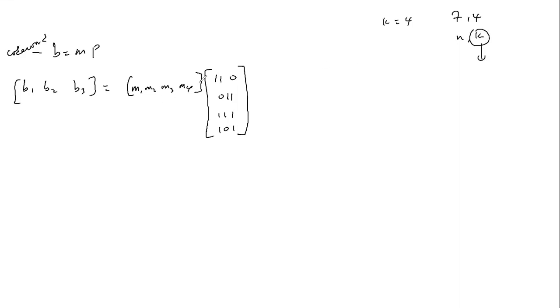So with this, we can develop the system of equations, such that B1 will be the same as M1 times 1, modulo 2 addition, M2 times 0, modulo 2 addition, M3 times 1, modulo 2 addition, then M4 times 1.